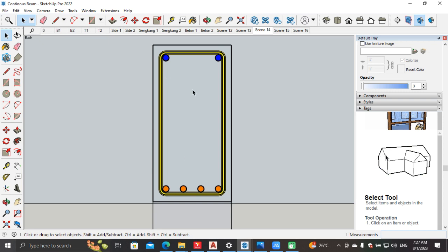That is the mid reinforcements, mid span reinforcements, and you have cut the 2 parts, which is given for the cage structure. Or else, if you are extending the top reinforcements, if you have that much money, you are extending the top reinforcement. Here also, you will have 2 bars, and you can label this. This is 2 numbers 16 mm, 4 numbers 16 mm, and you can also mark the stirrups. So this is the first diagram. That is, sorry, second diagram.